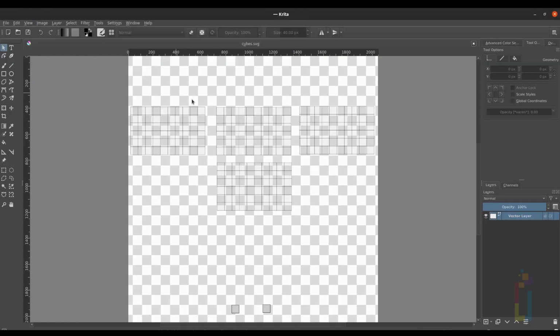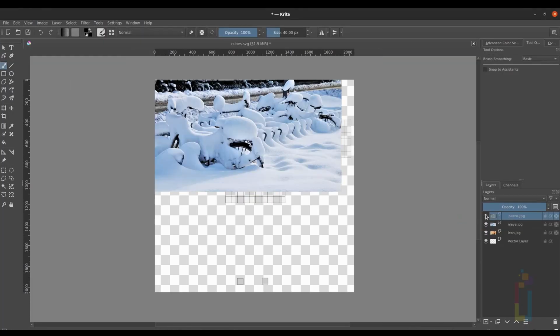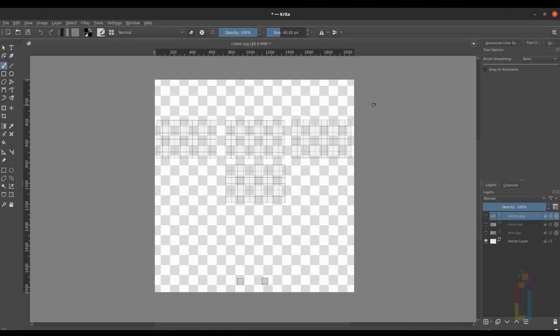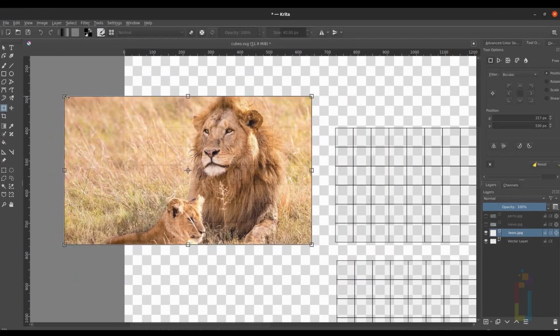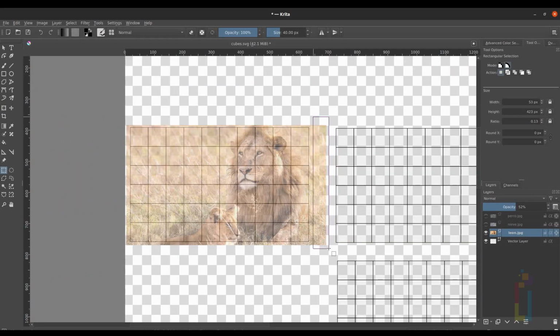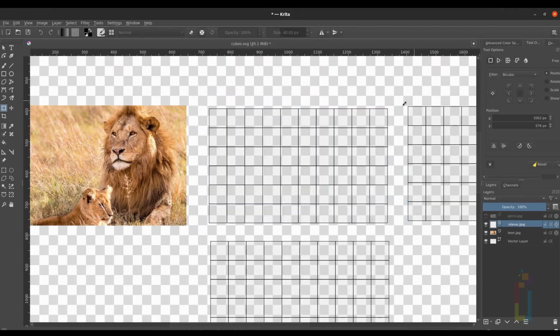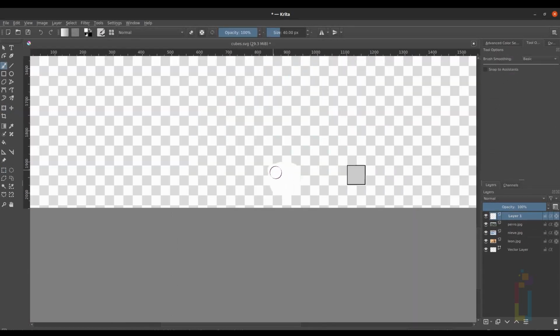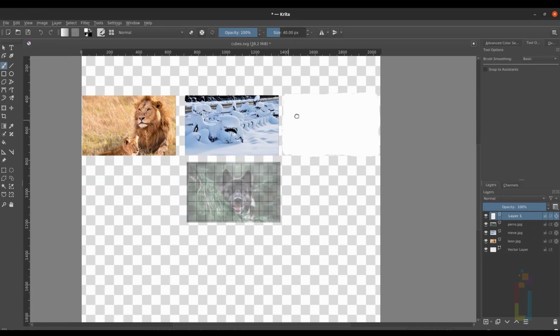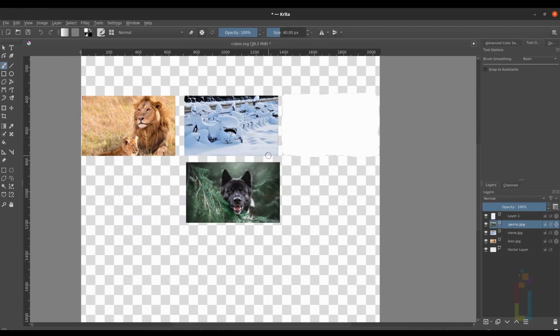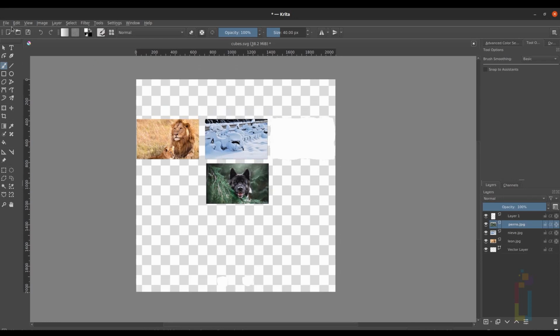Now open the UV layout using the image editor software and add the image and align all of the images above the UV layout. Make sure that all your images are only a bit bigger than the UV faces, like the one that I'm doing here. And if you need to, delete part of the image that is outside the borders. Once you finish that, you could add some colors to the sides that you're not going to use. Finish with everything, and once you have everything done, export the result as a JPEG or PNG.